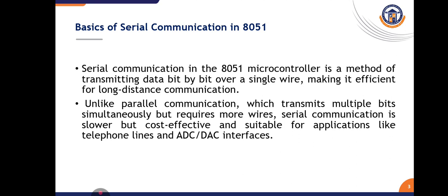It allows communication over long distances with minimal signal degradation. The microcontroller converts the internal parallel data into serial form, then transmits it over one or two lines, one bit at a time. When the microcontroller receives serial data, it converts the data into parallel form, so that the internal data processing becomes seamless.